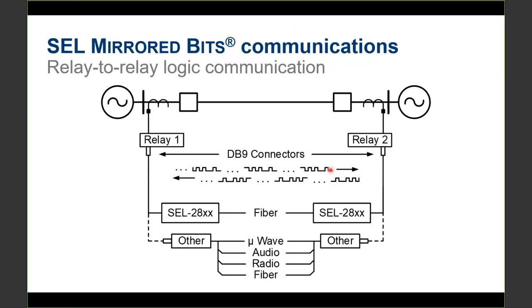But the mirrored bits protocol is completely different. It's a protocol to provide communication between relays. The idea here is to set up the relays to exchange information with each other using the mirrored bits protocol with low latency. Mirrored bits communication can be applied in protection pilot schemes, remote device controls, relay cross-tripping, and many other applications.